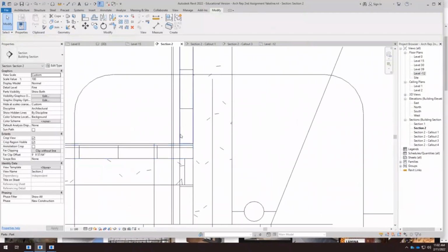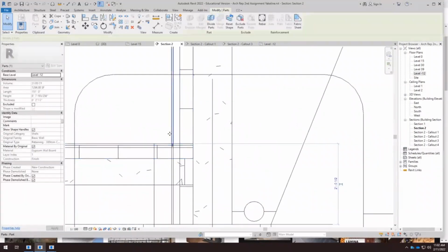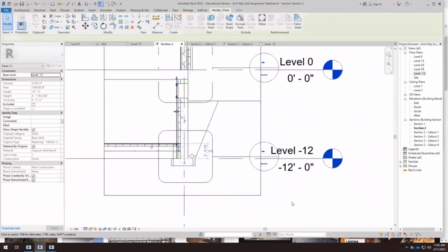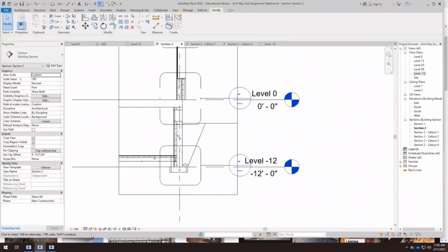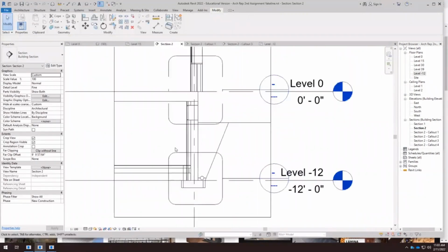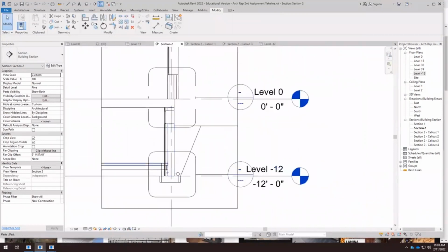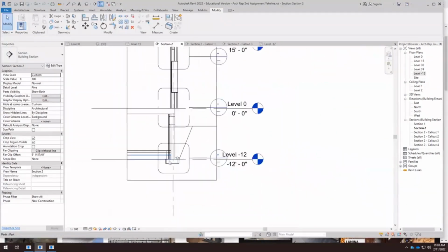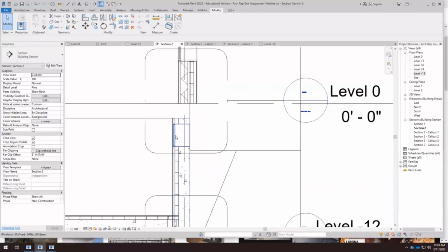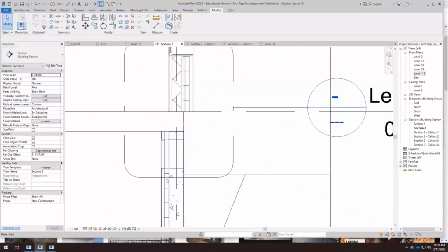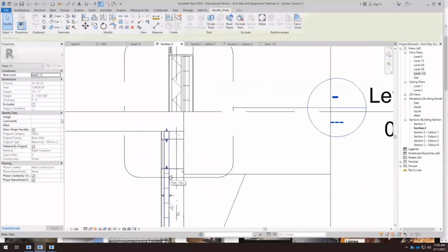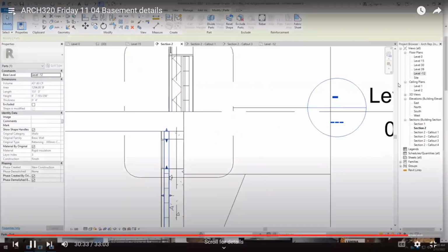Finally, this is the thermal insulation. This is the air gap. This is the gypsum board. And now that thermal insulation goes up to the floor slab, then we have to move this thermal insulation down, yeah, so that we close the gap without thermal insulation.